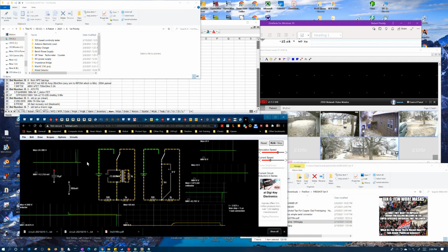You know, so you take it negative. Okay, now we're only getting like a 24 volt spike here and a 43 volt spike here because we lowered the ratio of impedances, and that's what's important, the ratio of impedances. So if you charge up at a low impedance, you're going to store a lot more energy in the coil, and then if you all of a sudden discharge it into a really high impedance, it's going to produce a very high voltage, but a very short discharge time. In fact, way shorter than your charge time.